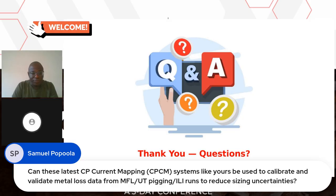Okay, so can these latest CP systems like yours be used to calibrate and validate metal loss data from ILI? Absolutely, yes, absolutely, to address the sizing uncertainties. Okay, but sizing uncertainties, for example, with MFL and UT methods for inline inspection.